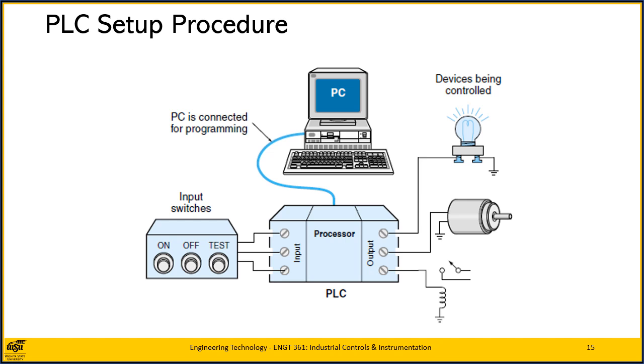The PLC evolved as a replacement for hardwired relay logic and was designed to be installed, programmed, used, and maintained by technicians who were familiar with industrial relay and switching circuits. For this reason, manufacturers of PLCs developed a programming language that allows the user to program the desired control logic in the form of a ladder diagram.